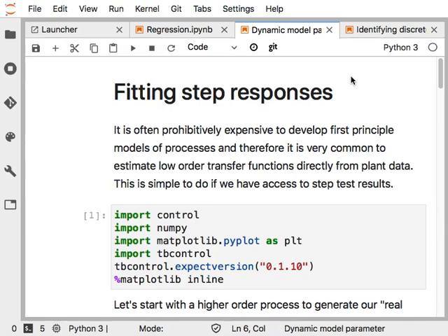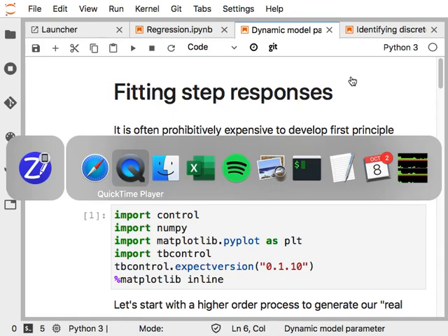But I want you to understand a very important thing. This idea of having a step response is very old school. It's very reliable. But right now, and when I say right now, I'm not saying in the time that the textbook was written, if you go onto a plant, very few people are doing pure step tests. What I mean by a pure step test is this idea that we've kind of covered to death already.